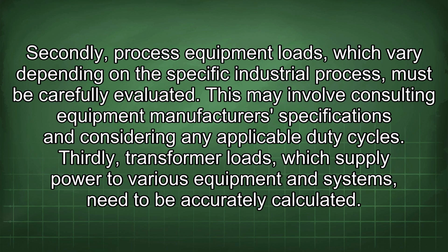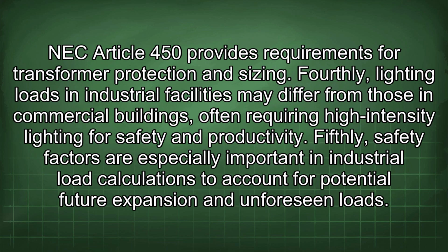Secondly, process equipment loads, which vary depending on the specific industrial process, must be carefully evaluated. This may involve consulting equipment manufacturers' specifications and considering any applicable duty cycles. Thirdly, transformer loads, which supply power to various equipment and systems, need to be accurately calculated. NEC Article 450 provides requirements for transformer protection and sizing.